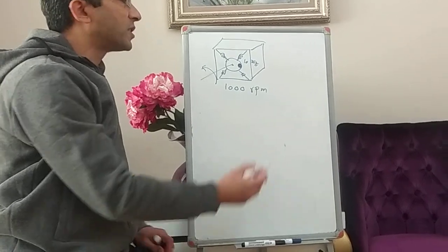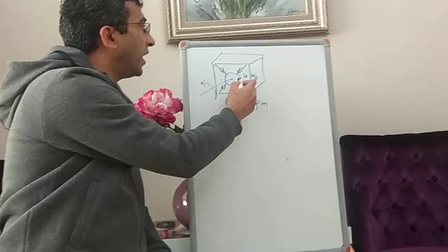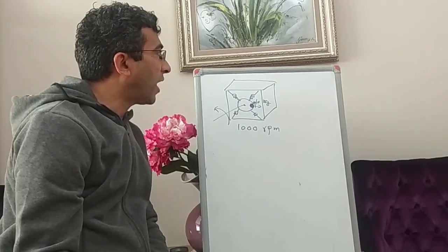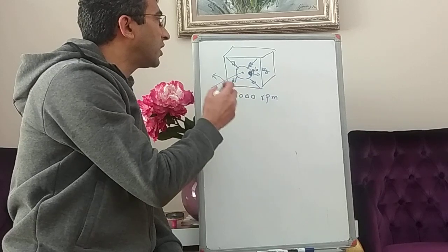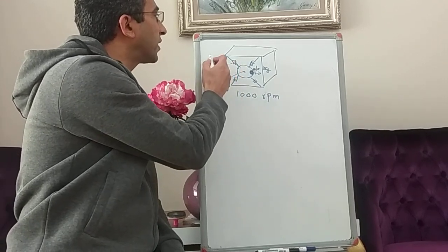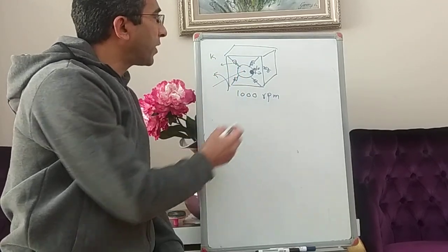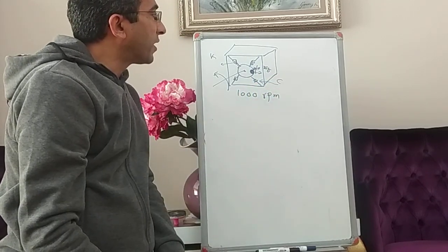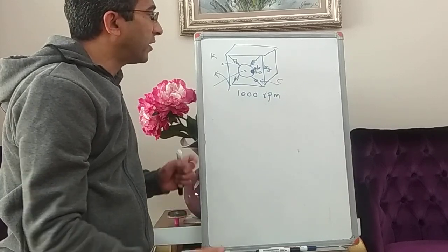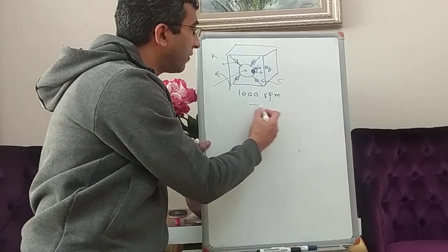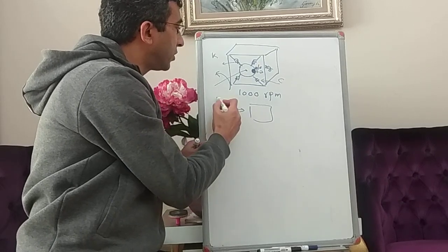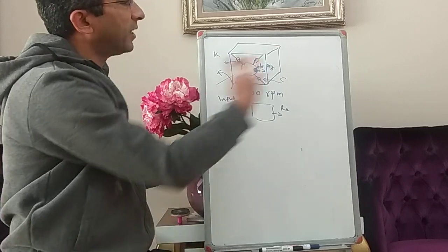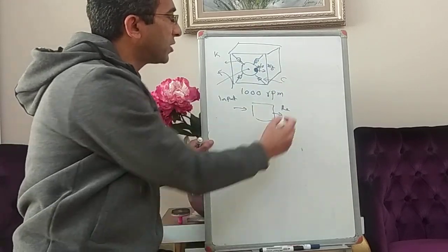And you want to reduce the lateral and vertical vibration. You don't want a lot of noise. So the engineer needs to find the suitable stiffness for this spring and the suitable damping constant for this damper. Again, as I told you in the previous video, you have an engineering system, you have input, and you have the response. My response is the lateral or vertical vibration, y.